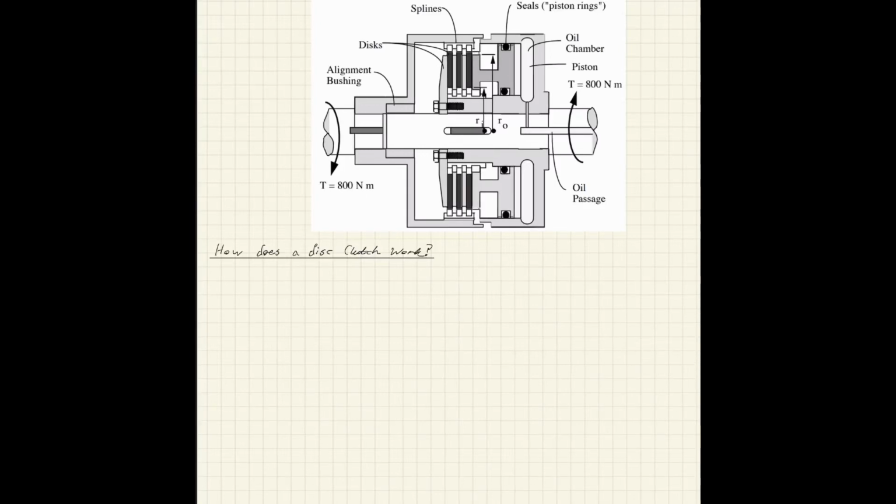In order to solve questions relating to clutches and clutch discs, we have to understand how a clutch disc works. Clutches are comprised of wound clutch discs and friction surfaces. The disc has a sacrificial friction material on it. In some cases, it's things like carbon or carbon ceramics oftentimes. And these are meant to wear away over time.